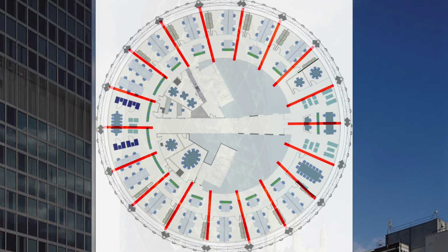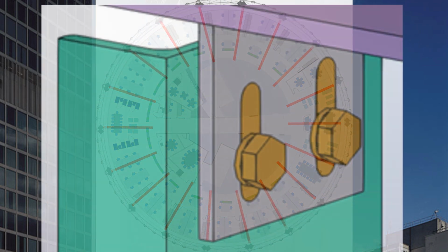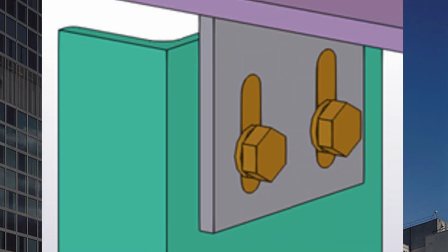Additionally, a laser transit was used. The error in construction was measured using a geo laser transit through the core of the node's central extension line. In addition, through a very delicate design, there was little error, but when a slight error occurred, it could be solved through the slot hole bolt method that could be corrected.